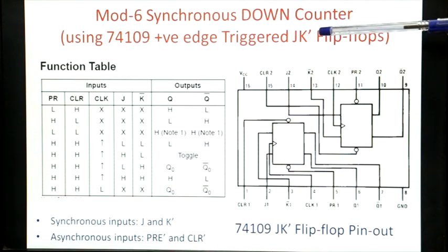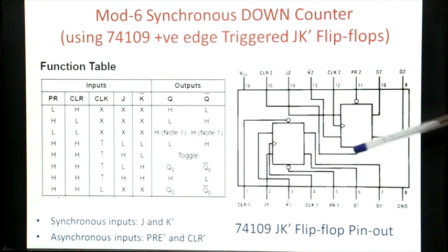If you want to design a delay flip-flop using a JK flip-flop, what you would do is connect your D input to J, and use an inverter between J and K. Exactly the same thing they have done here, so that you get that functionality. But unfortunately, this gives us trouble for our design.